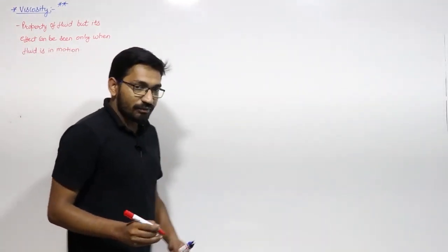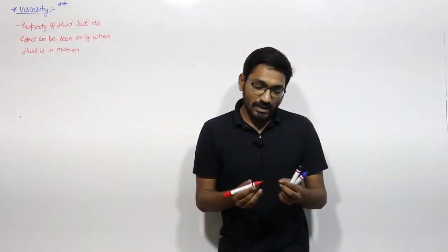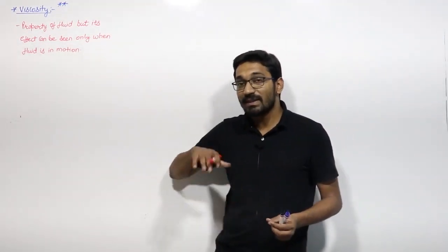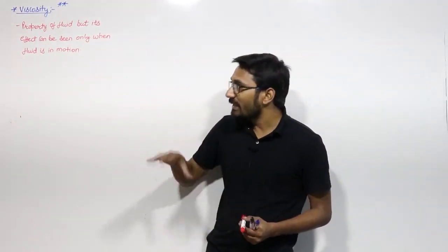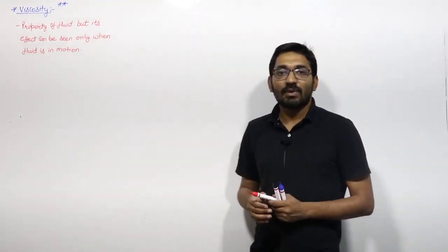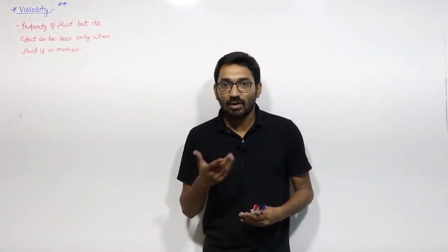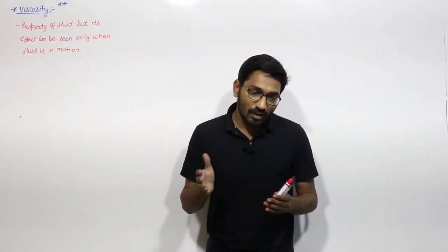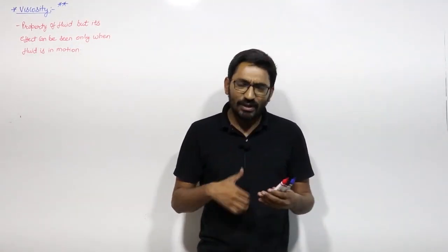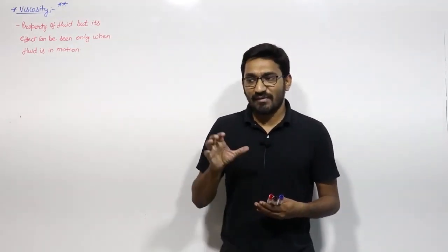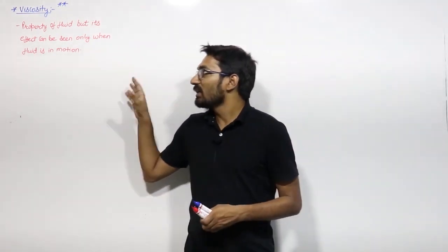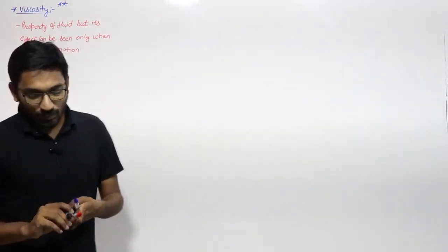Viscosity is a property of a fluid, no doubt, but the effect of viscosity can be visualized, can be seen, in a fluid only when the fluid is in motion. If the fluid is at rest, there is no concept of viscosity. You cannot say what the viscosity is at that point. You cannot see the viscosity effects when the fluid is at rest. So its effect can be seen only when the fluid is in motion.